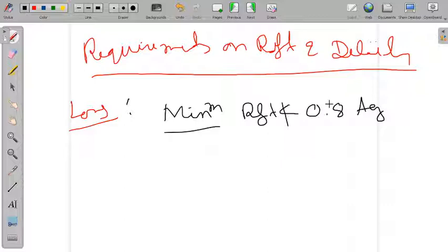However, in case of pedestal, generally pedestals are plain concrete columns, still in that case also we have to provide a minimum of 0.15% of the gross cross sectional area. Then again it says about reinforced concrete walls, because that is also a compression member.